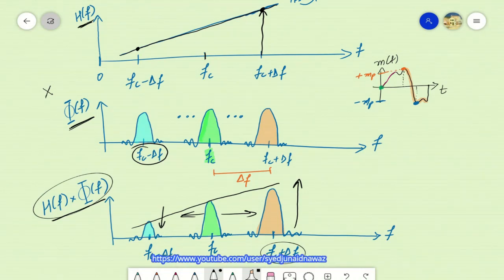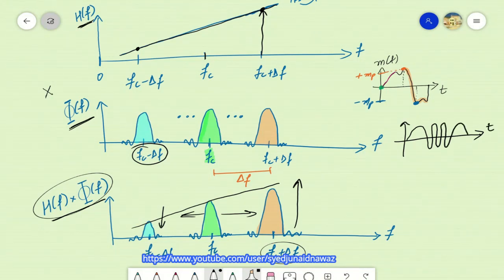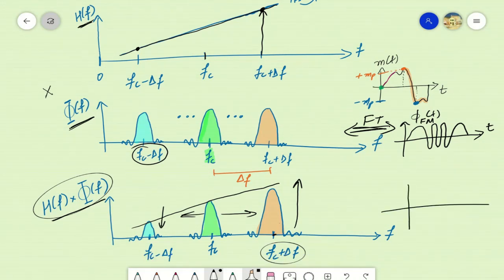which represents exactly the derivative operation. If a frequency modulated signal, where frequencies were being fluctuated with respect to the information signal along time, was fed as input to this filter, which has a Fourier transform as equivalent to this signal, after passing it through this filter, frequency dependent magnitude scaling is caused here, directly proportional to the frequency of the signal.